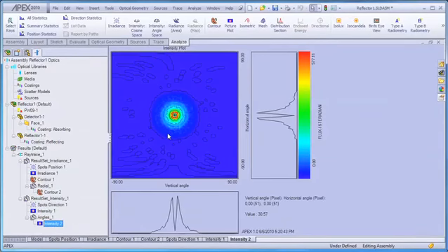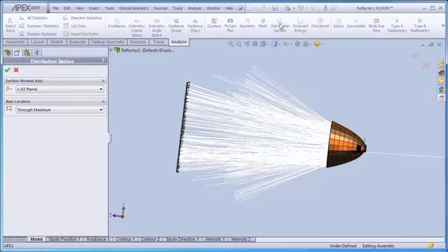We've plotted the same distribution information in angle space, and we can again see that the bulk of the energy is contained in a central ring around the optic axis, but that we have a hole in the center. Now finally, we might choose to create a distribution section, which in this case gives us the option of creating a cross-sectional view of our far-field intensity.